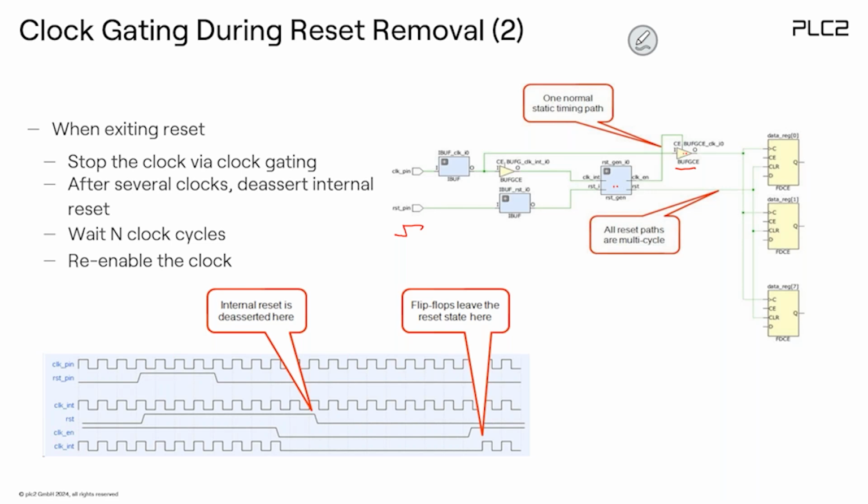Okay, this means that because you switch off the clock, there is no clock signal here. Now, the reset has enough time to propagate, because if there's no clock, there's no timing variation. And when you deactivate the reset later, the reset will be deactivated, but the clock is still disabled. After a while, the reset generator will again enable the clock, and then the reset signal is stable.